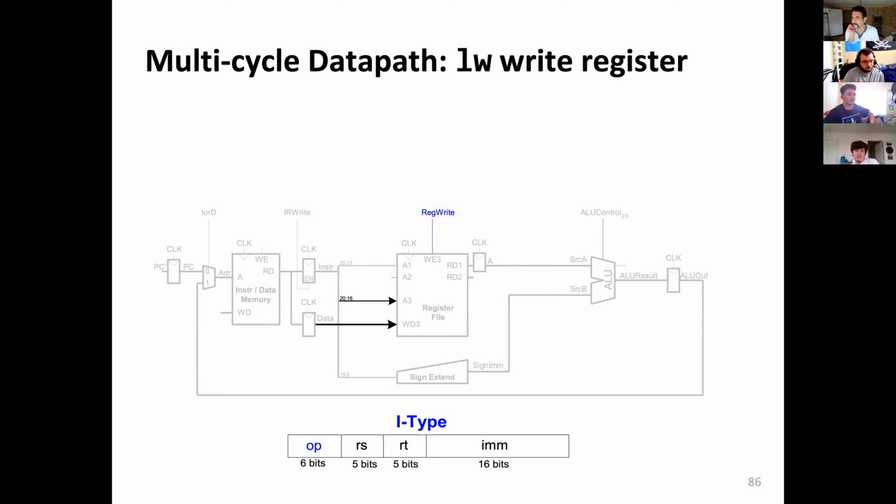Yes, Ross. So are we trying to utilize, it obviously depends, there are different types of flip-flops, like toggle, set, reset. Are we trying to set those sorts of things up while we're doing the instruction, basically? What are we trying to what? Like with flip-flops, you have different options depending on the bits, whether you get a 0 or a 1. By flip-flop, you can think about this as a register. It's not 1 bit. It's like 32 bits. Like you should have enough storage here. It is an array of flip-flops, right? So you should have 32 bits here in order to store the instruction, right? So you have enough storage, it's not 0, 1.